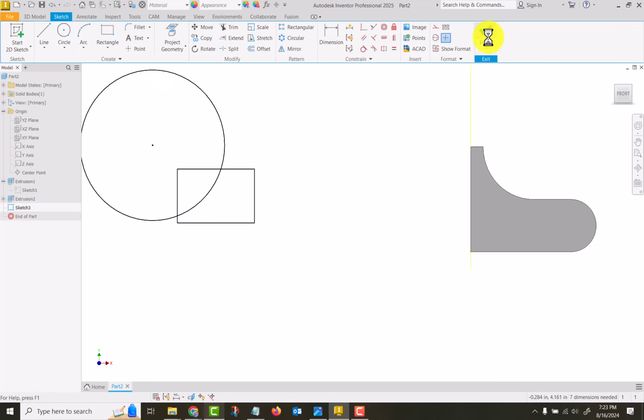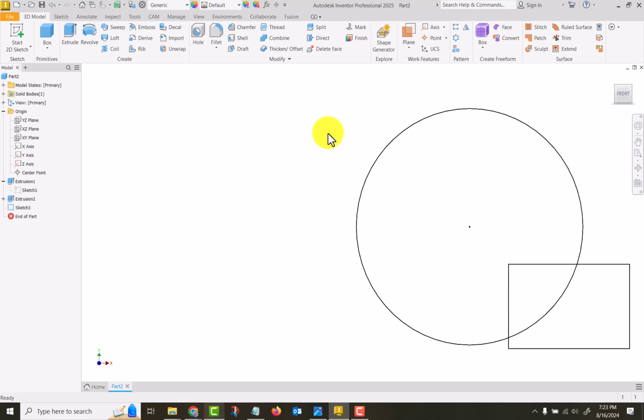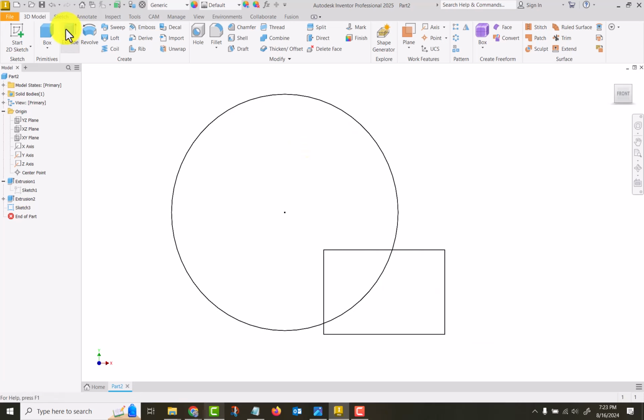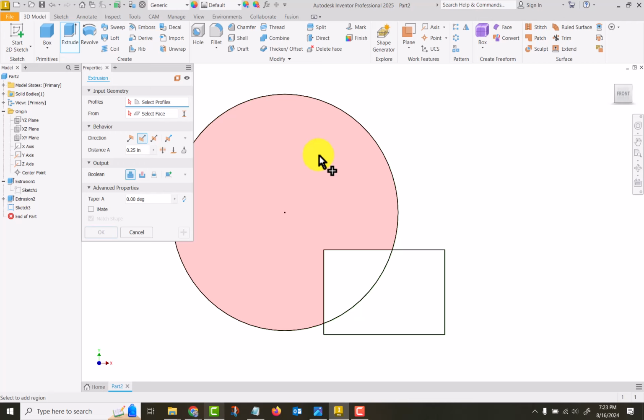And so if I go here to extrude, if you notice, I can pick various parts of what I'm doing here. Okay, so this will extrude just that part of the circle in pink. This will extrude just that part in the pink there. This would be just the outside edge. If I were to choose just intersect, I still get the same options.